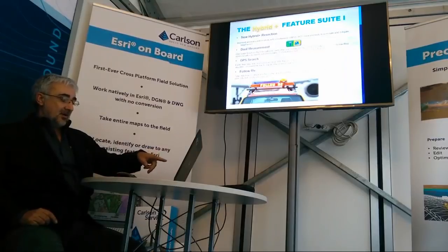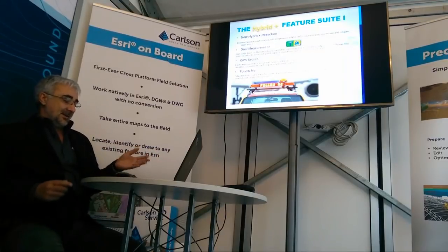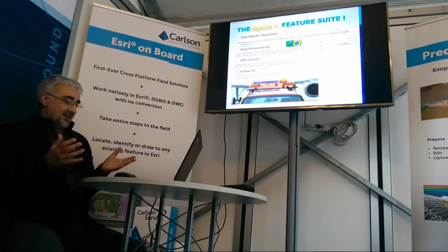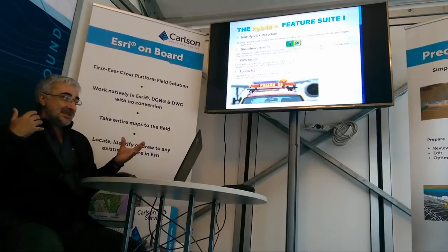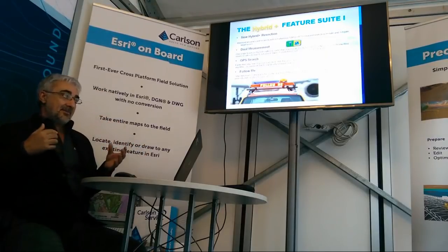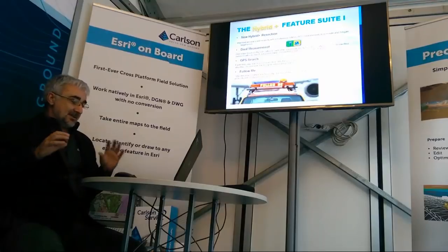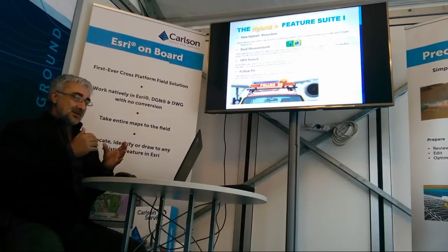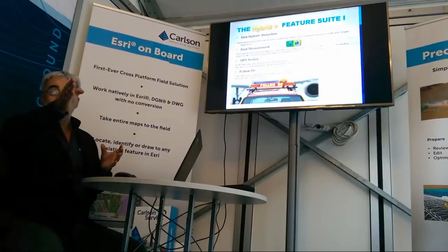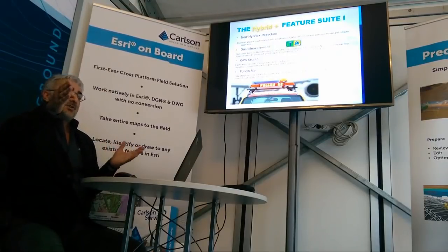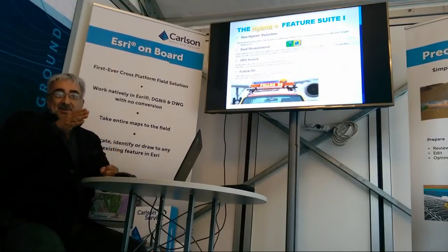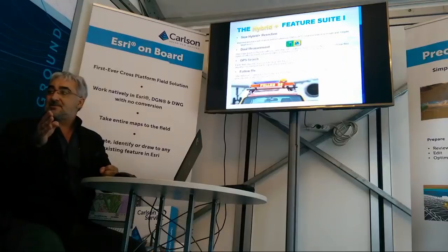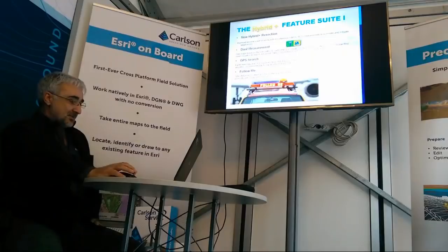Follow Me is doing exactly that. If the instrument is losing the prism, then it will at least be close to you all the time. Every 3 seconds, you can configure that. It's a bit hidden, but you can change it. Every 3 seconds, it goes to your place, your GPS place. Not trying to lock the prism because it's not necessary, but keeping close. Why? Because when you need it, it is a very small rotation of 3 degrees to lock the prism and continue working. So efficiency again. Right? So that's what Follow Me does.